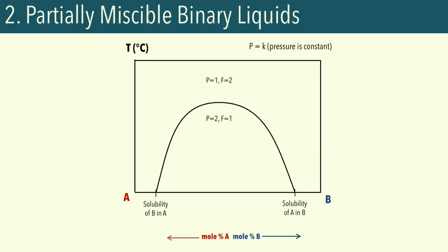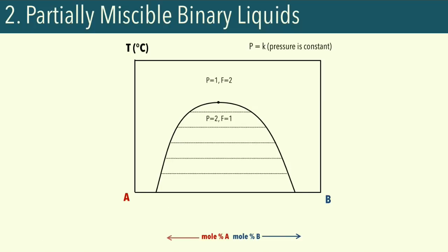Very similar to our treatment for our ternary phase diagram, we could also use so-called tie lines to determine the corresponding composition of those B-rich and A-rich layers. This time, however, the corresponding tie lines are going to be parallel to one another. At different temperatures, we expect to see different tie lines, and all those tie lines are going to converge at a single point over here.